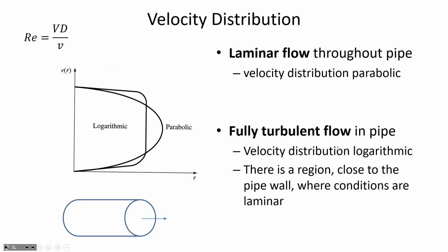All right, when water's flowing through a conduit, the water in the middle of a pipe, which is further away from the edges, is going to have a larger velocity because of the no-slip condition. So remember, it is that stationary pipe applying a shear stress to the water that is resisting flow. And so the further away you get from the edge of the pipe, the water is able to flow more freely. So in the center of the pipe, where you're the furthest away from the edges, the velocity will be the highest.